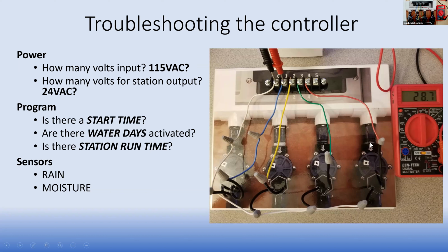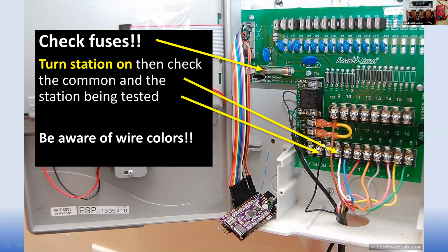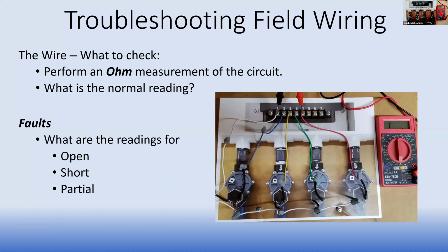You would also want to check the fuses on your controller, make sure everything is good there. Otherwise you can spend a lot of time if it's just a fuse. Make sure all the fuses and fusible linkages are actually good as well. Okay. All right. So what we just did, when we were going through that, was find our resistance measurements.